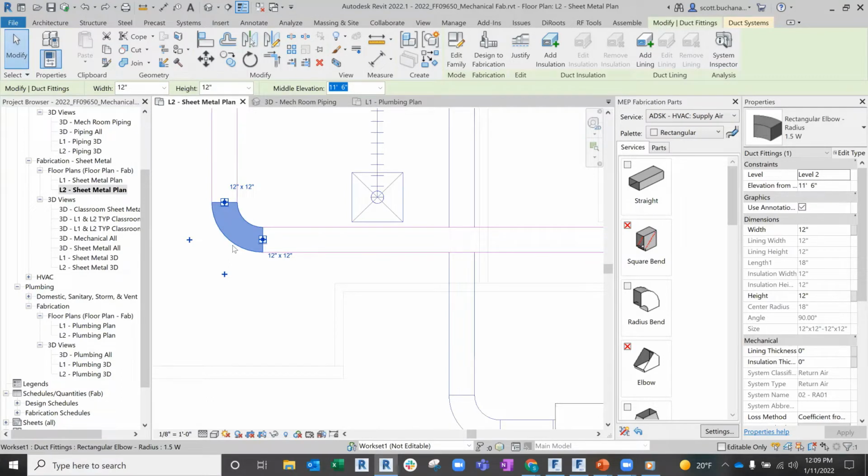But one thing about content in Revit from an MEP standpoint, on the piping and the sheet metal side, is that Revit has no idea what a real connector is. Okay, so that little snap point right there, that's all it is. It's just a snap point, and it means that, hey, this thing can snap to this, and they go together. No matter what, they go together. So you can think of it as, if you had an incompatible piping service, let's say you were running copper into a stainless steel line. If it was just Revit content, because they have snap points, they're going to connect. Okay, so it doesn't understand the logic of an actual connector. There's nothing that defines it other than size.